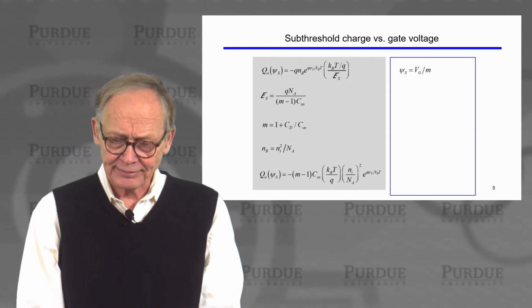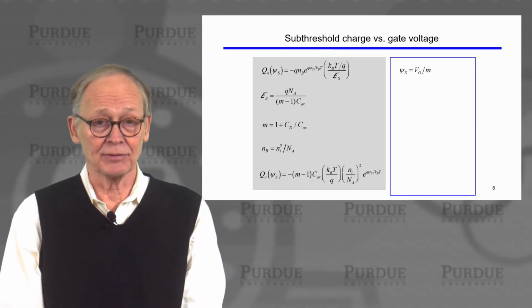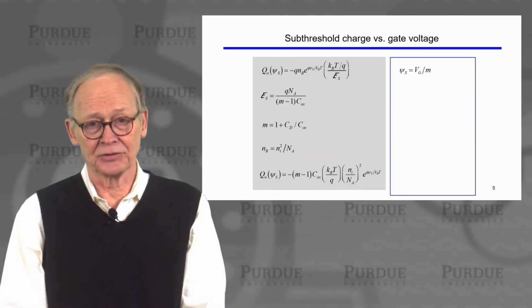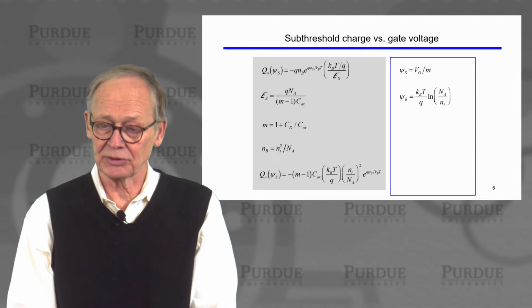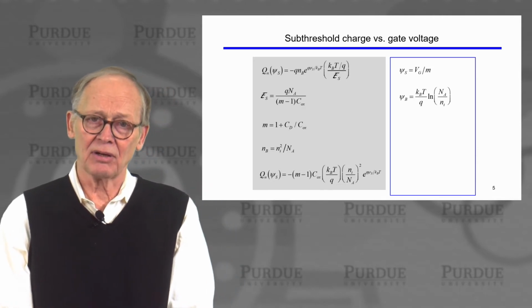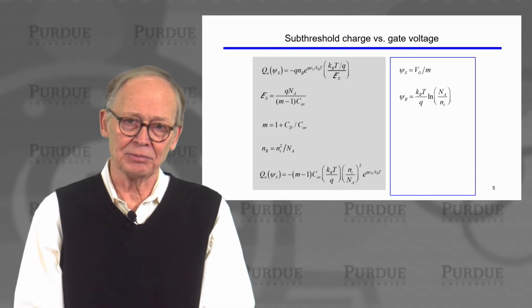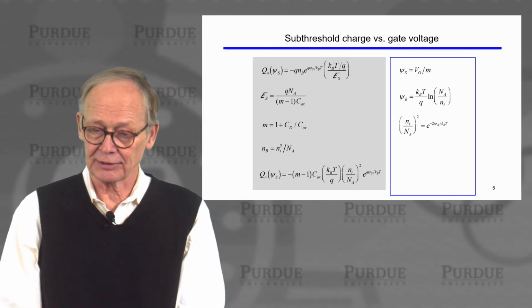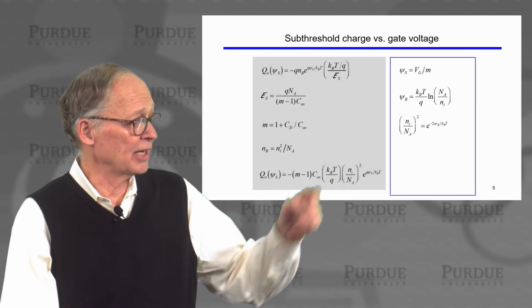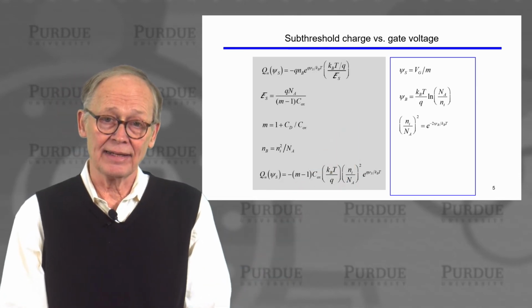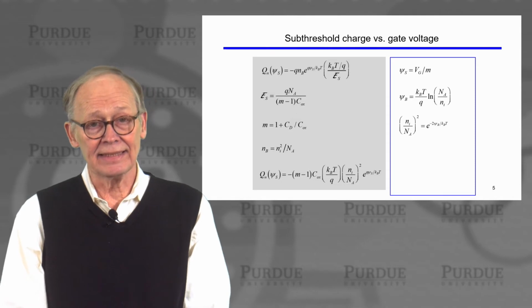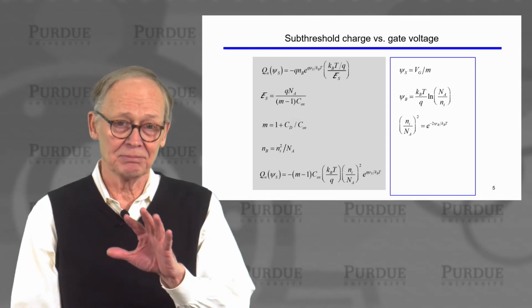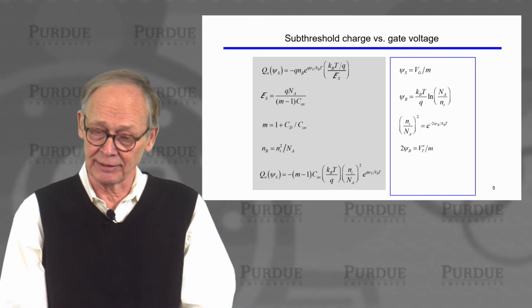Okay, now, we're trying to relate this to the gate voltage. We're using our approximate two-capacitor model to say that the surface potential is some fraction of the gate voltage. Also recall that this key parameter psi sub b, which tells us how much we have to bend the bands to invert the semiconductor. You can easily show from that relation that (Ni over Na) squared is e to the minus 2 psi b over kT. So stop and prove that to yourself if you don't see it immediately.